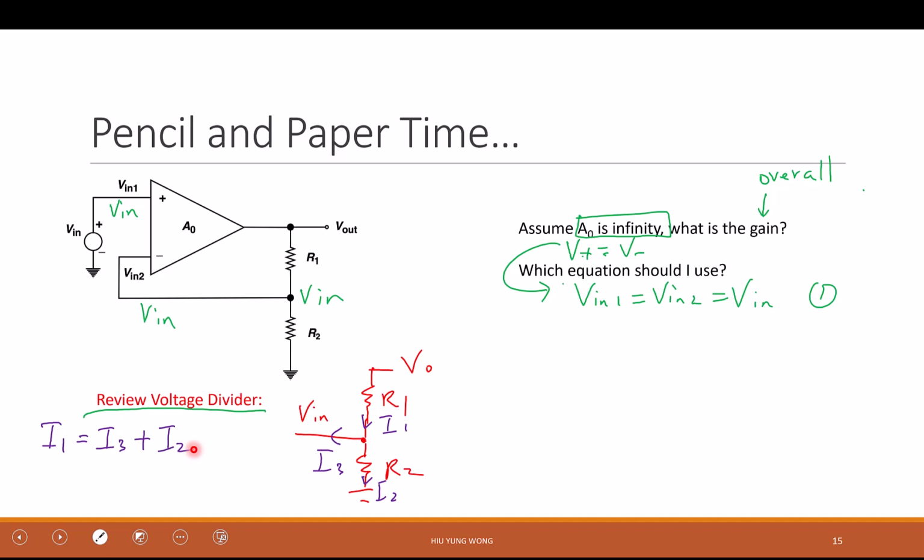You don't even need to think about KCL. Of course, it got the name because they derived it in a more rigorous and physical way. Otherwise, this is common sense even for a baby. When water flows on a river, it needs to add up. It needs to be the same as what branches to the left and what goes forward. That's intuition. So I1 equals I2 plus I3.